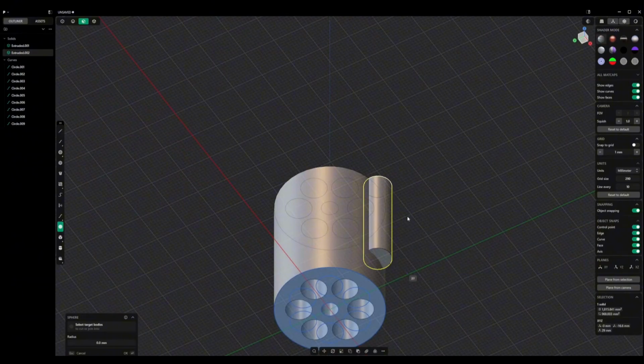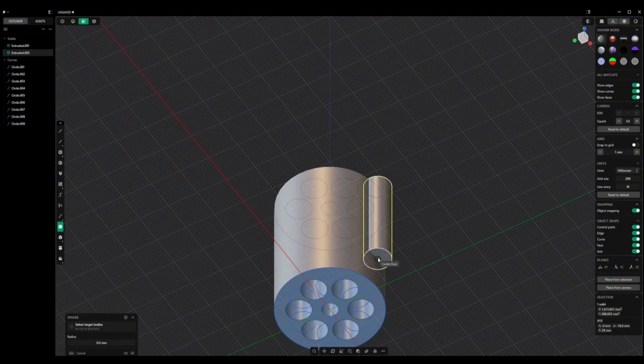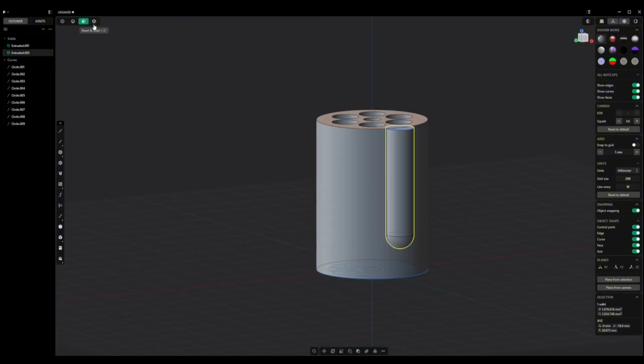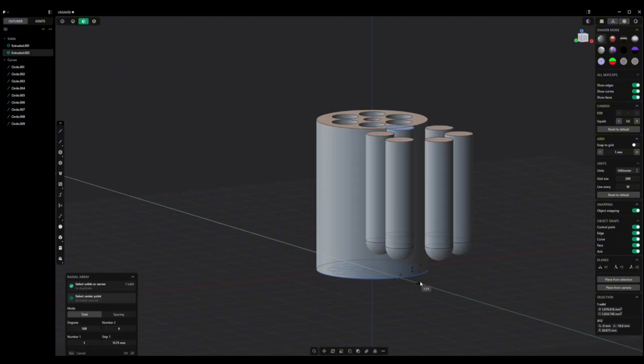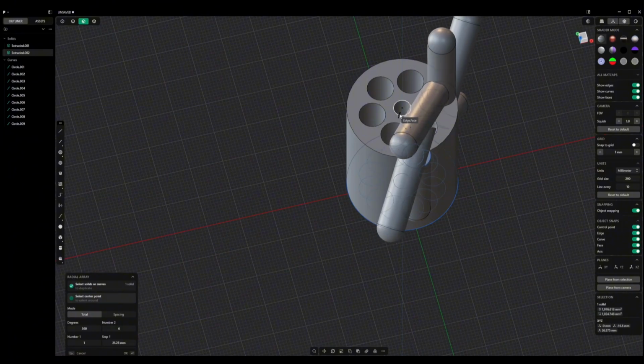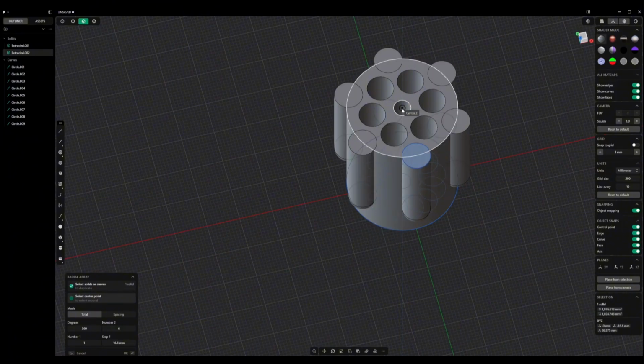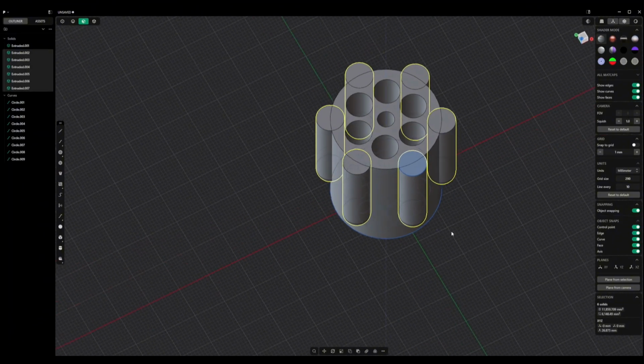Now we'll go underneath and then we'll make a sphere here. And you want to make sure you press Q so that way you're adding and you're not subtracting. And you want to make sure it lines up to the end, the outer edge of this shape here. So we're going to press end there and then we're going to press right click. Now what I'm going to do is while I have this all selected, I'm going to click on radial array. And now we're going to make sure it aligns to the very center of this object. And we're going to left click and then right click.